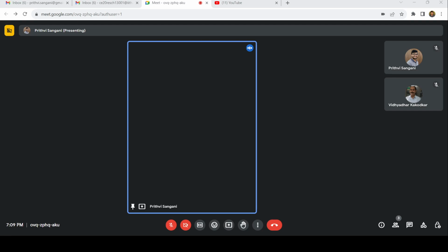With that, what will we find? m plus r minus 2j. Number of members we have 1, 2, 3, 4, 5, 6, 7, 8. Reaction forces 3. Minus 2 times the joints, 1, 2, 3, 4, 5. 11 minus 10, that is 1. Mind you, this is not the joint.